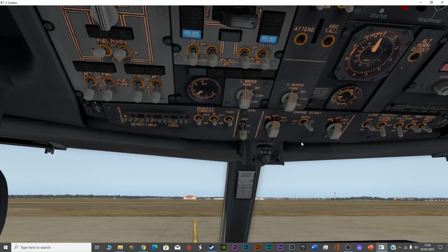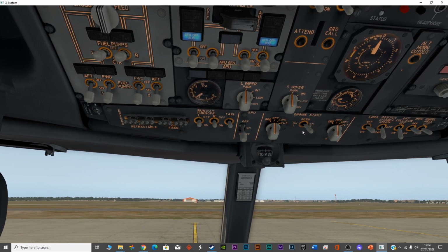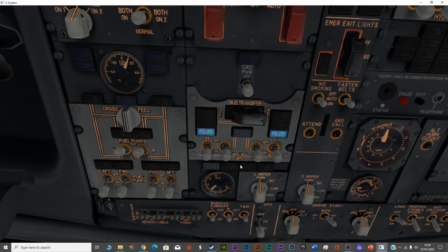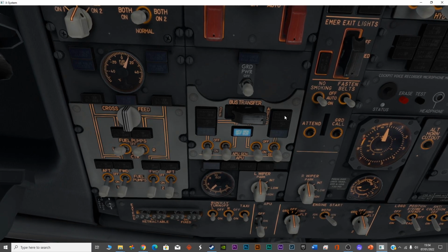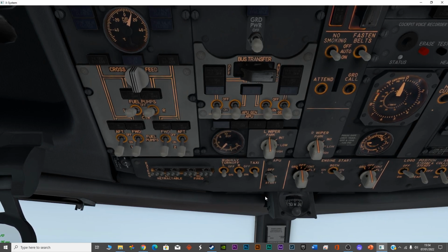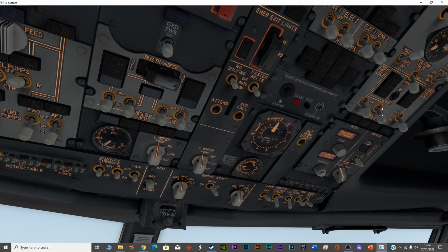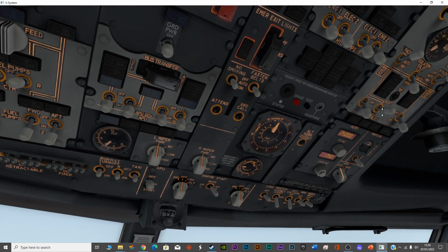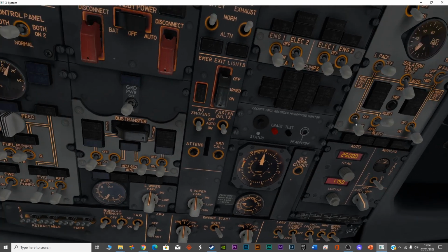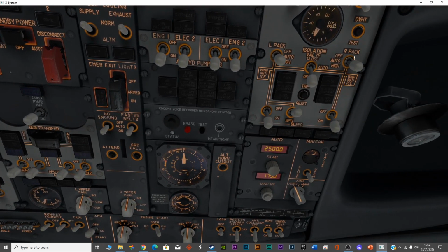Now it's time to basically turn on the engine generators, so that now the generators are running on the engine. Initially we turn on the APU generator from here, now engine. Now the power is on the engine generators, and this time we can turn off the APU because APU is no longer required, and you can turn off the APU bleed, and packs to auto to get back the air conditioning. And you can see this is up now.